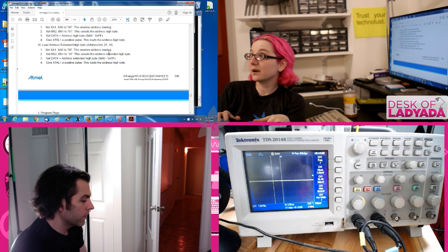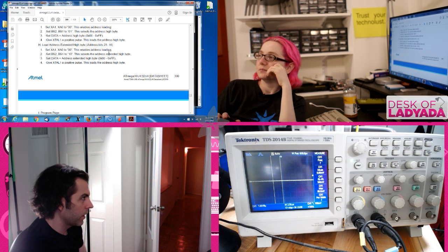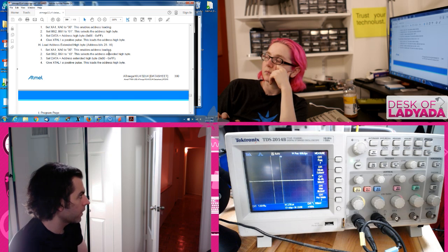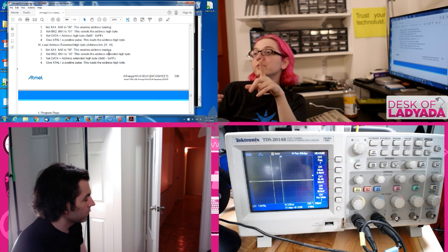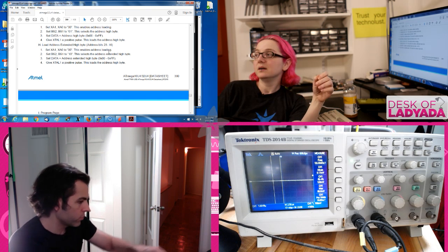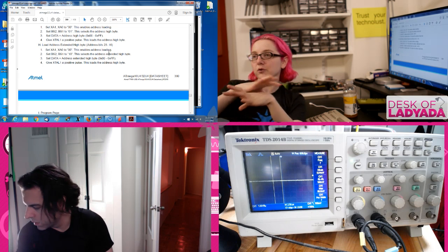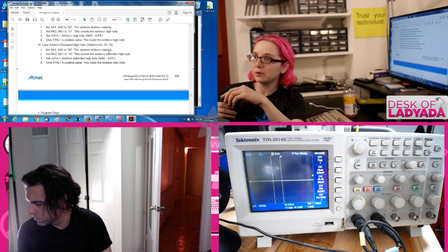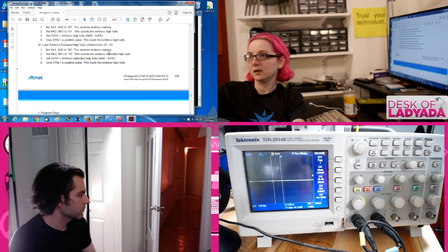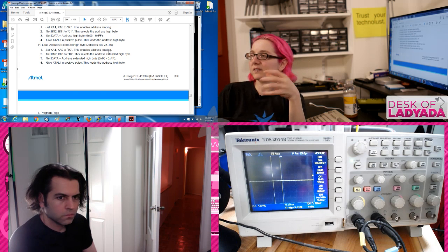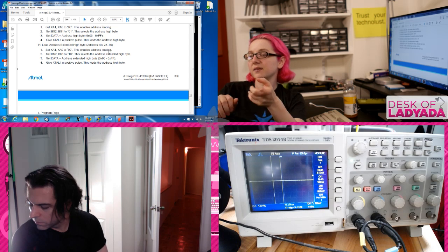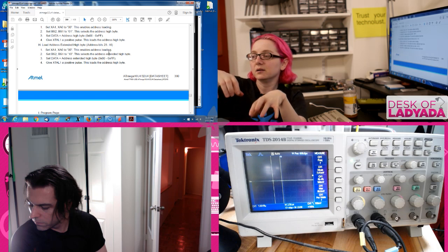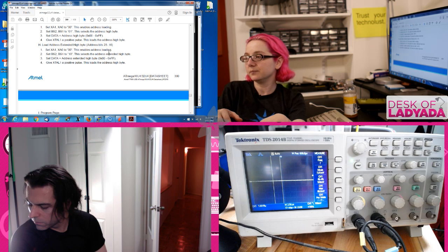Okay. This is neat, because I know what this means. We're just going to have a whole slew of testers that will probably speed things up by a third or more. And another cool thing is you'll be able to run them in parallel. People ask, why don't you do batches, like 10 at a time? You can't do that if you can only have 1 ST-Link or 1 J-Link connected to a computer. But if you have standalone testers, you can. I mean, it's tough. If it takes less than 30 seconds, it's not worth it, because it takes the same amount of time to put it in and out of the tester. But in theory, you could have an entire panel, clamp it down, and have parallel programmers. It's all possible.